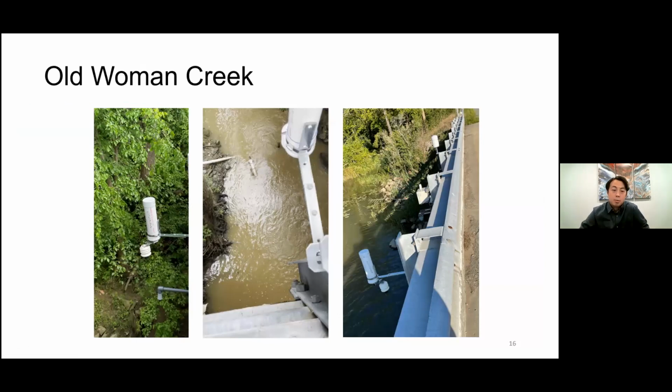At Wolverine Creek, this is a river slash estuary environment. We were able to mount these water level sensors on bridge structures to measure the creek water level throughout the whole network. We were also able to do a comparison study, comparing the classic sensors to the more affordable sensors and the quality between them, which I will get into later.